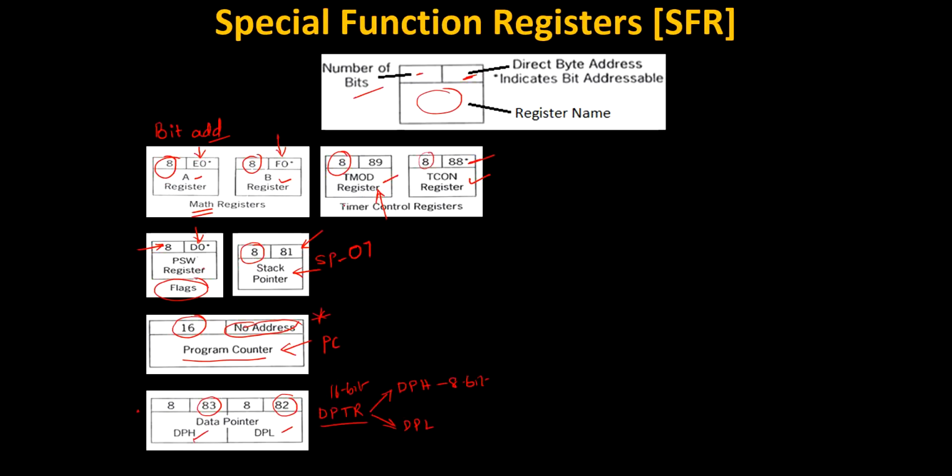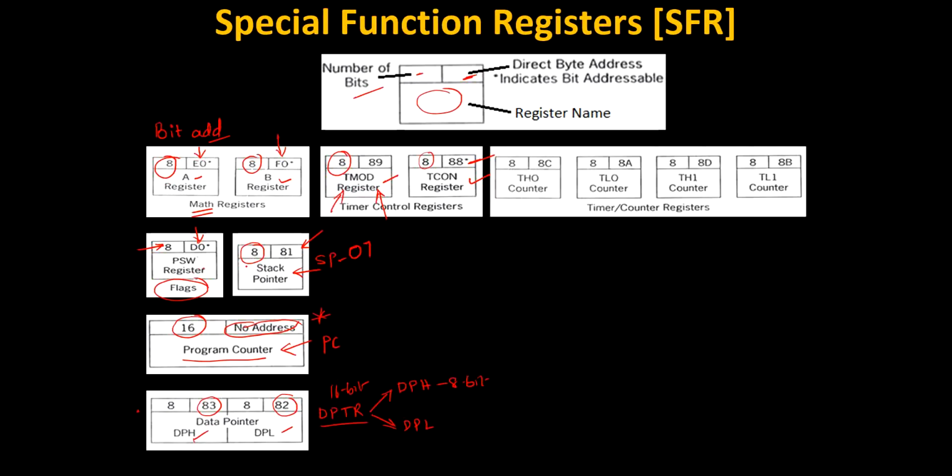It is also an 8-bit register. So we can generate a clock frequency and a delay, which can be configured through this register, and the mode of operation, mode 0, mode 1, mode 2, will be configured by the TMOD register. So with the timer registers, we configure which timer I can use, timer 0 or timer 1. Remember, these timer registers are not bit addressable; only TCON is bit addressable.